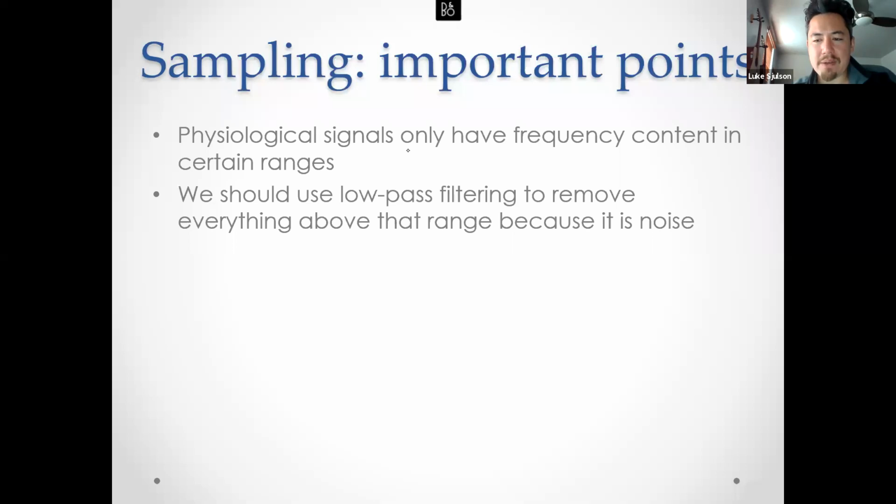But also a microscope, right? If you think about having a camera on a microscope, the number of pixels you need, or the packing of the pixels, has to be more than twice as high as the frequency cutoff in the point spread function of the microscope. So the microscope itself is acting like a low pass filter on the distribution of fluorescent molecules. How many megapixels you need depends on the spatial frequency response characteristics of the microscope.